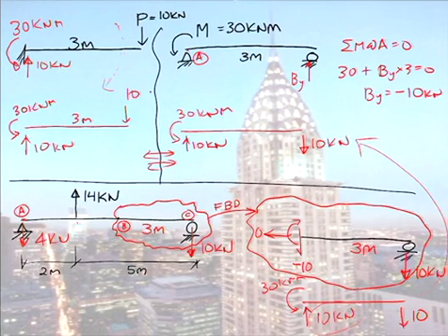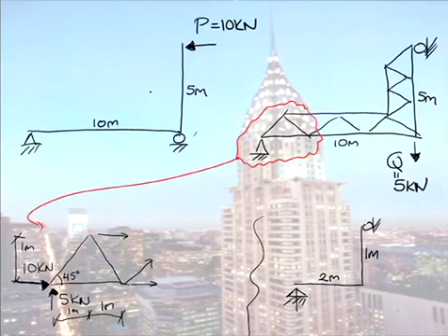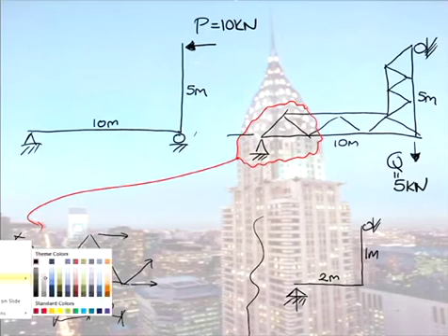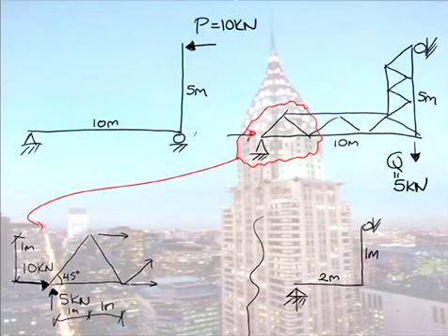Just to stress that point one more time, because I've thought of it, it's a bit messy. Again, this was the truss from the previous page. We had a 5 down here. When we worked out our reactions, I'll just do it in red, we got a reaction here, I believe, of 10 and a reaction up of 5. So if I now say, okay, I have to do a method of sections and cut through here, my loading, my reactions, are 10 and 5.